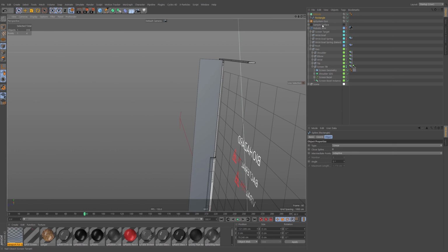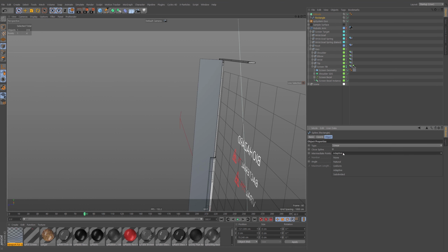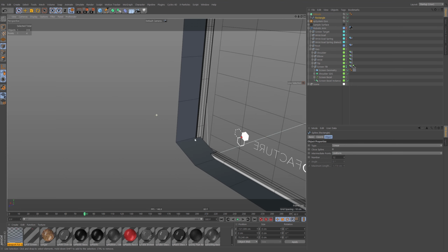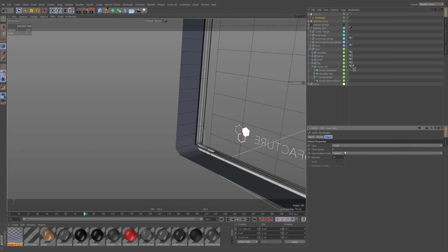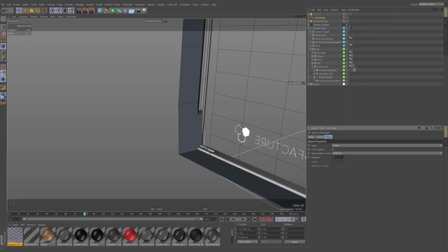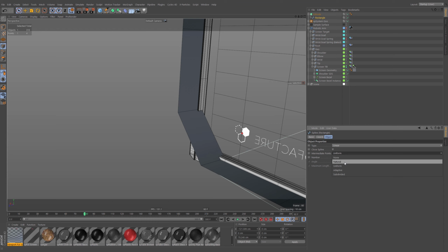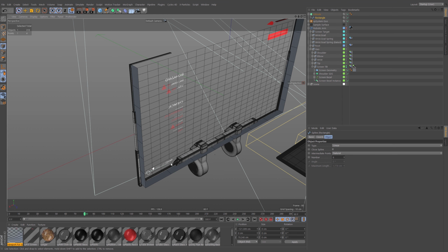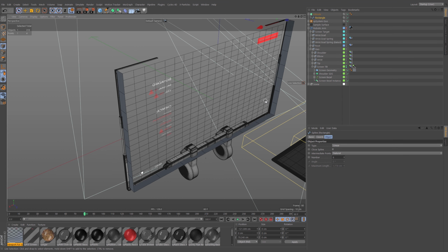What we want to see is when I go into my rectangle spline and I change it from another mode. So I could use a uniform mode, you can see there, that's creating these nice subdivisions. The problem with this one is when you have these 90-degree angles, if you don't have a perfect ratio or enough divisions, you'll see that corner curves up. And we don't want that. We want it to be perfectly 90 degrees in that corner. So the other one we could use, I guess, is natural. But natural would also vary the spacing between our points. And I want it to be quite grid-like because imagine it's like some kind of quantum pixels or some sci-fi excuse for that.